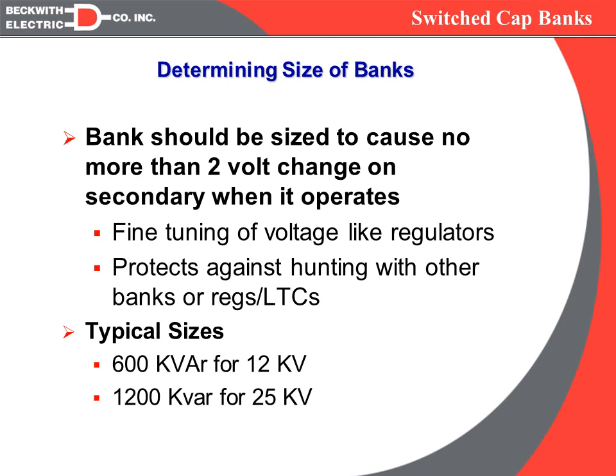So we want to be fine-tuning just like a regulator. One of the goals here is to reduce single-phase line regulators with switch capacitor banks, because switch cap banks are much less expensive and much easier to maintain. With a regulator, we know we've got 16 taps plus or minus and 10% regulation total. We want to try to get close to that with cap banks, and therefore we want to have more, smaller cap banks. And we need to protect against hunting on the LTCs or the regs.